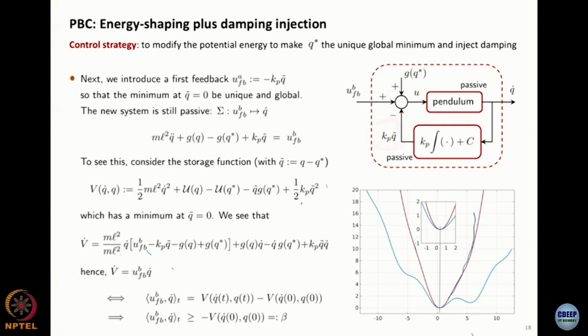So it's this proportional term. It's a feedback of Q dot if I pass it through an integral. So an integrator is a passive system, right? It's the simplest passive system you can think about. So y dot equals u, v equals y squared. That means that v dot is equal to y times u. Passive system. An integrator is a passive system.